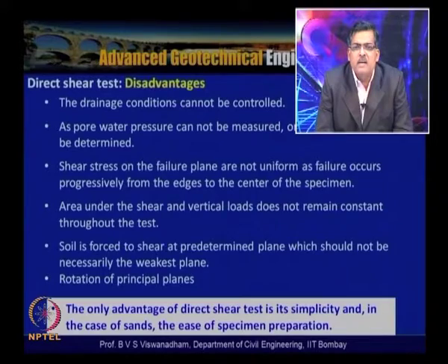In such a situation, we are regarding the failure as taking place along a predetermined failure plane. Another disadvantage of the direct shear test is the rotation of the principal planes. As we have seen, during shear the principal planes undergo rotation in the direction of shear, and the angle of rotation of these principal planes is approximately estimated as the inclination of the failure envelope with the horizontal, that is the friction angle.